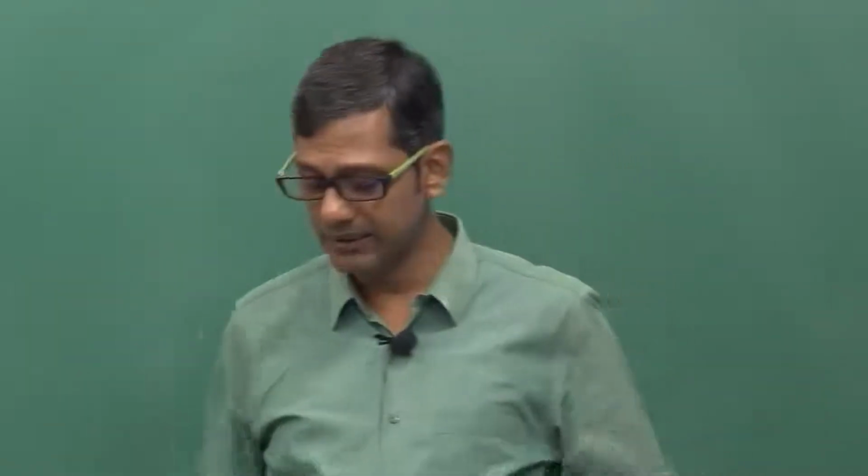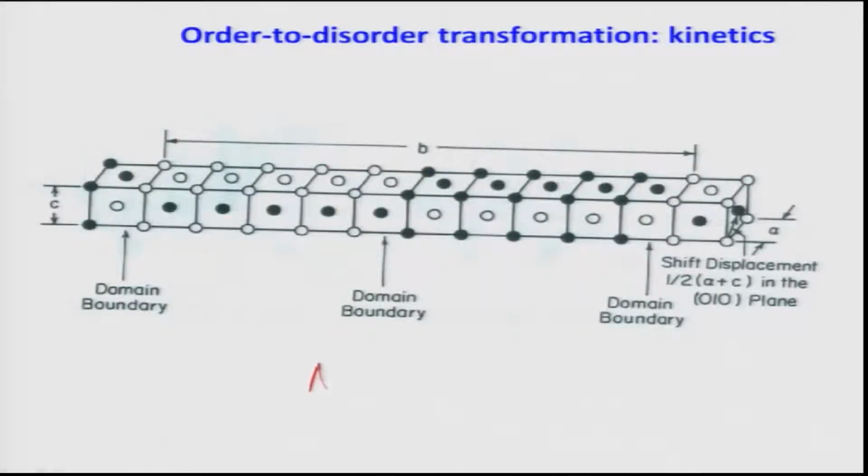So, next, the last thing which I would like to talk about is that even in the case of the gold copper structure, in the case of the AuCu structure rather, the one which I showed you, which is the L10 structure, as you clearly see here, the unit cell is longer, much longer. Why? Because here the unit cells have joined, remember that this is the simple FCC unit cell, which is a disordered structure. Again there is an ordered structure, there is a reversal, and then there is again a reversal here.